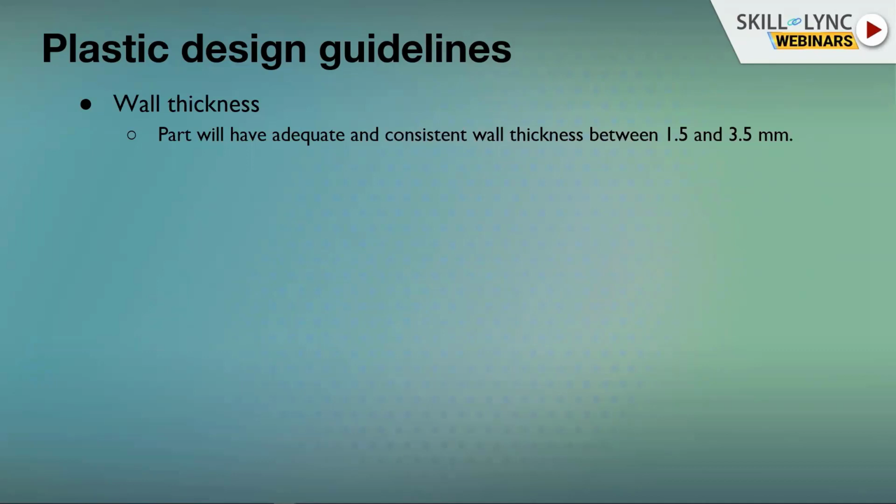Wall thickness strongly influences many key characteristics like mechanical performance, feel or appearance, and also moldability, right? The optimum thickness is often a balance between opposing tendencies like strength, weight, durability, and cost. When you define a wall thickness, you should give careful consideration in the design stages to avoid expensive mold modifications and mold problems in production.